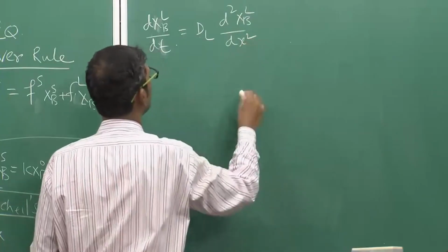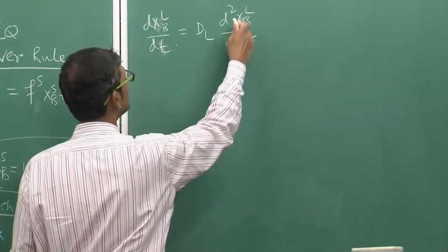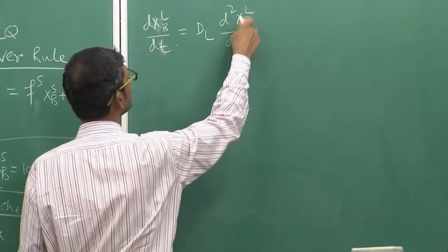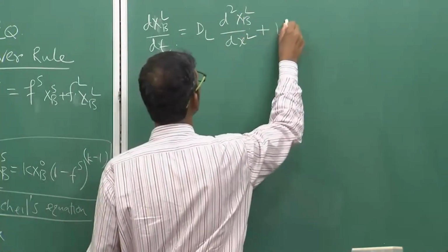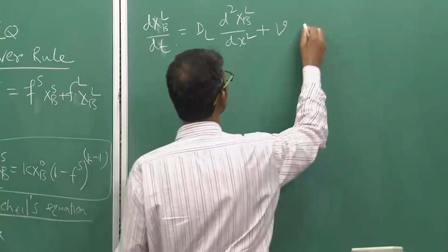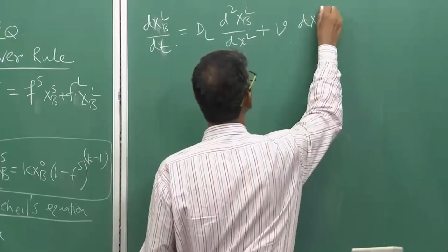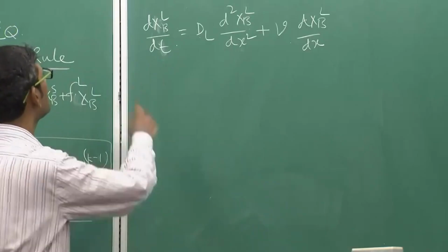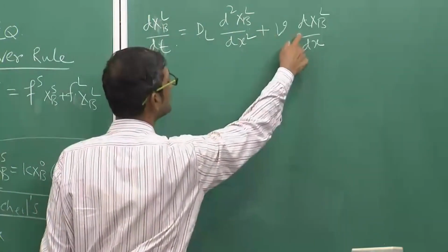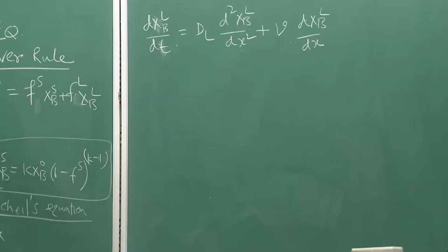in the space and time, the small x is the space, capital S, when you have superscript, subscript, that tells you the composition, the small t is the time, plus v is the velocity of the interface. Remember this is my diffusion equation, we do not have this term, the third term on the right side of the diffusion equation.